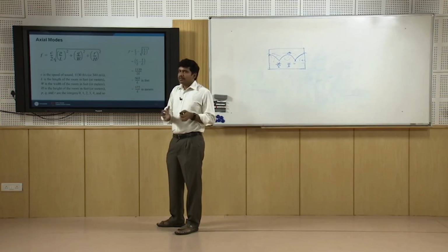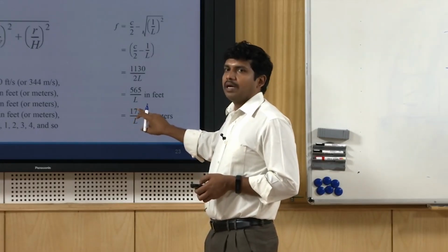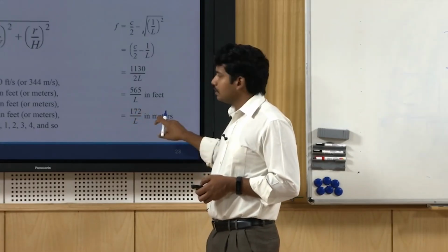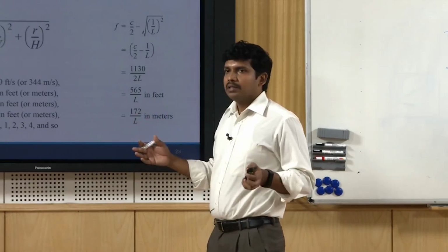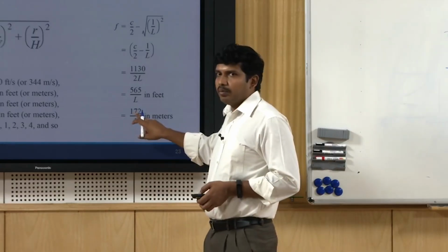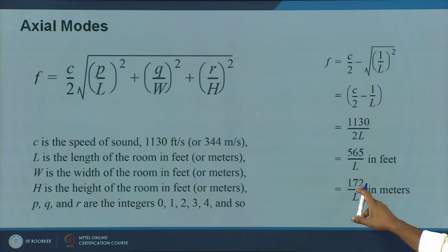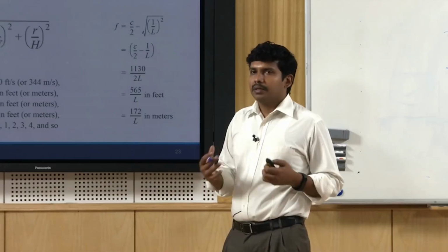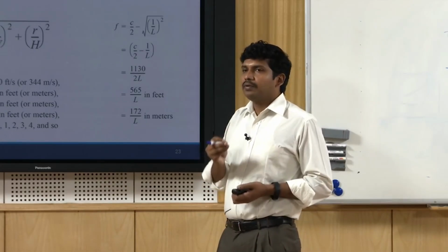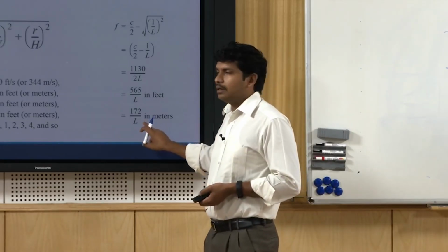comes down, any dimension of the room comes down, you will start experiencing room modes at slightly higher frequencies, whereas if you have wider rooms, the room modes occur at very low frequency, marginal. Say instead of 4 meter room, you imagine a 10 meter room, the first mode which can happen would be somewhere around 17 hertz, which is more or less what your ear cannot detect. So it is not a really crucial thing, whereas if a room mode is occurring at 100 or 125 hertz, it will be a crucial thing to address.